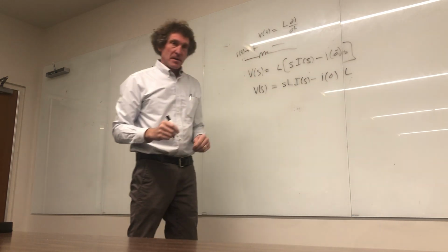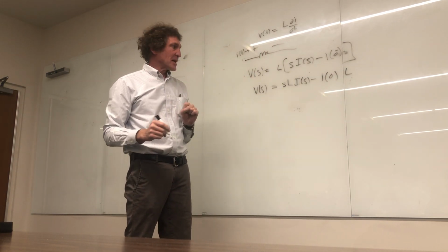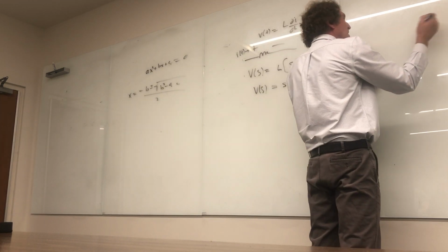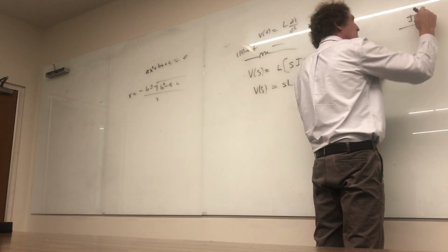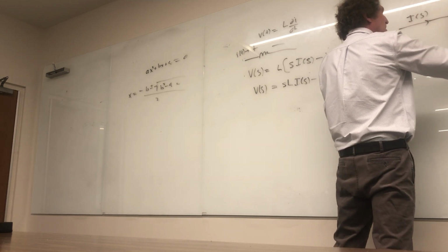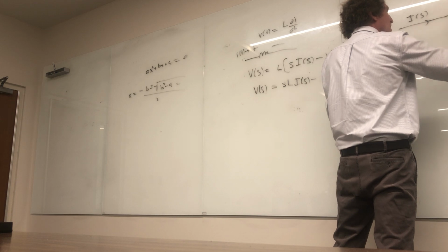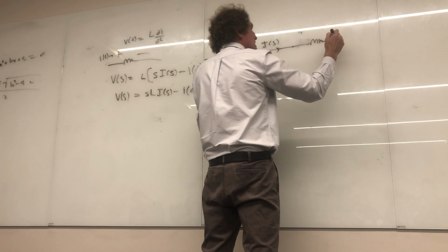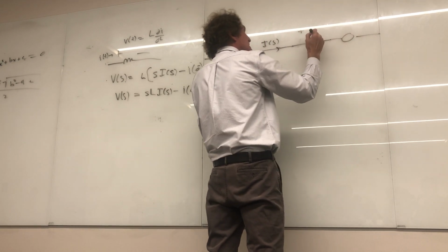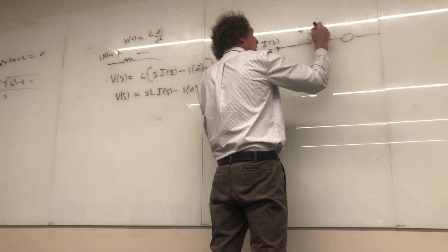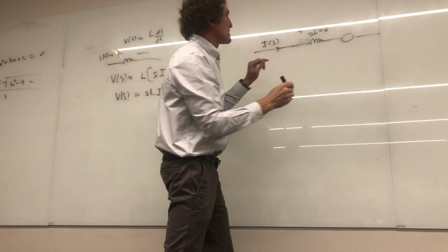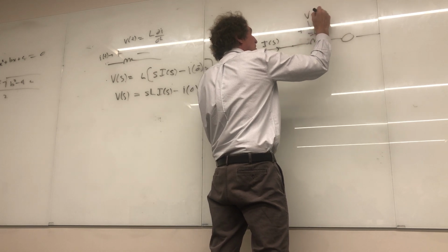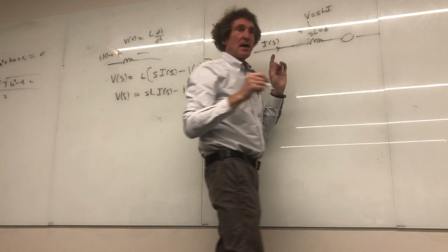So what does that look like? Now, just follow me on this and you'll get it. What you're going to say is this: if I have a current here, I of s, and I'm flowing it into an inductor here, it will develop a voltage that will look like this. It looks like this has the impedance sL, and put a Z down there. So to get the voltage on this part, the actual voltage right here would be equal to sL times I. You got me on that?